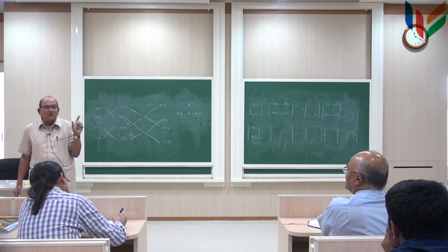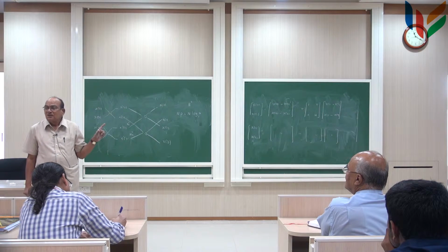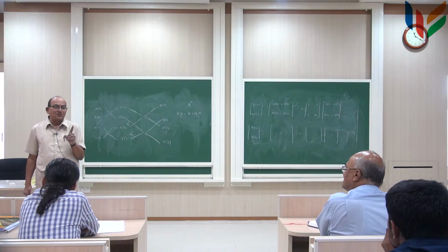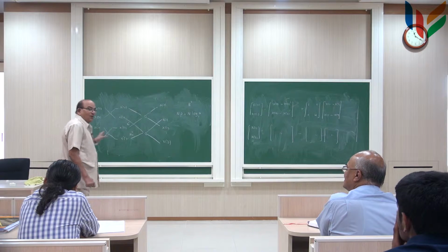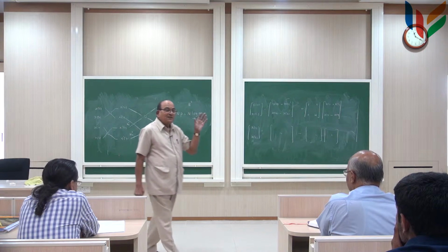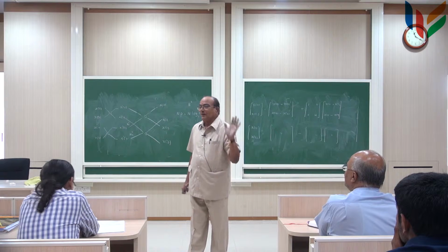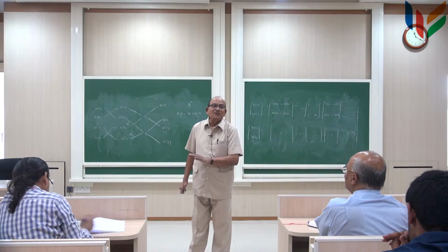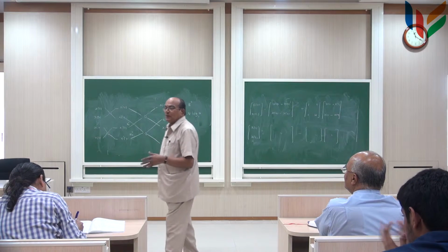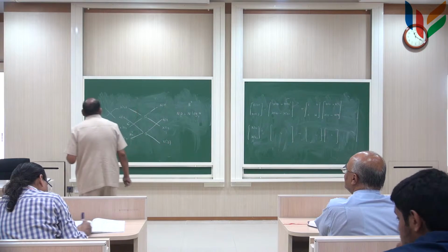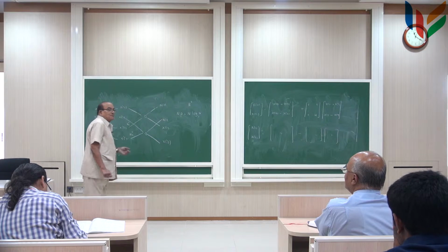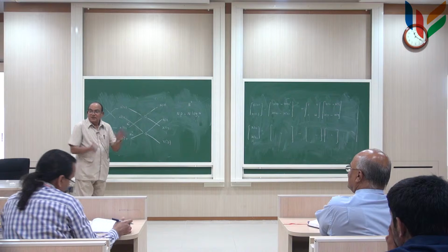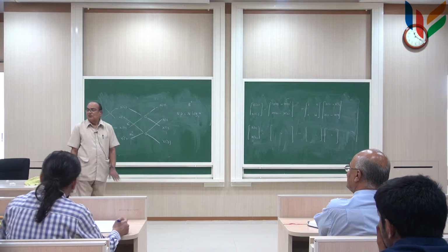And if you look at it very critically, all he has done is to use the principle that w to the power of n plus k is equal to w to the power of k. That has simplified the whole thing because of the cyclic property of the e to the power of j function. He has very intelligently done it by reshuffling the way of doing it.